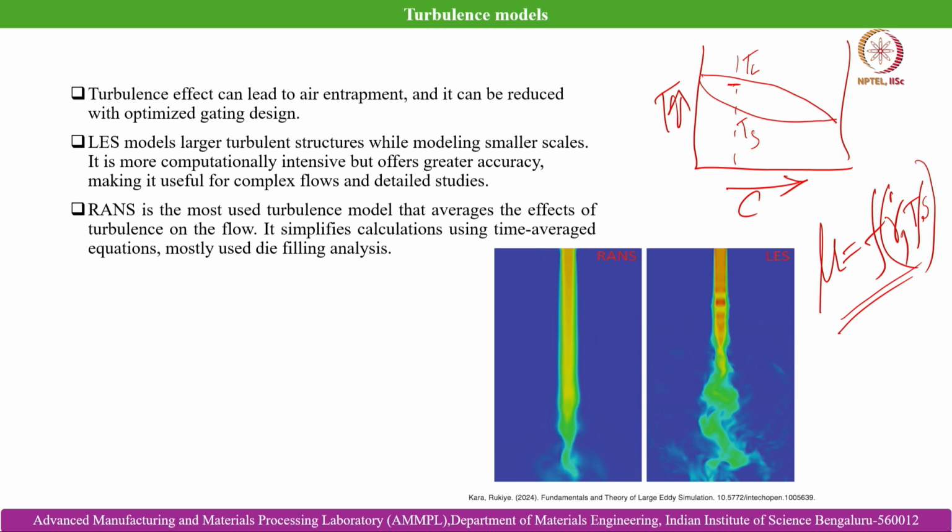So it is a challenging thing that we experience in die casting, and that air entrapment can be reduced by effective die design. For example, in case of light metals like aluminum or magnesium, we can try to adopt the principles of a non-pressurized gating system, and in that case we can achieve relatively lesser turbulence even in high pressure die casting or in gravity based die casting processes.